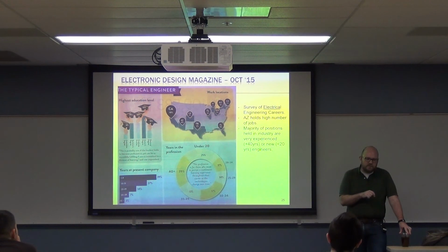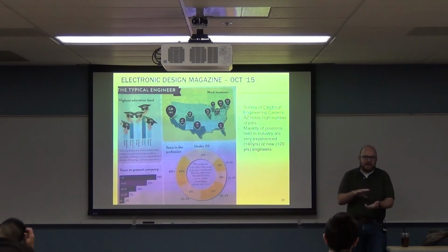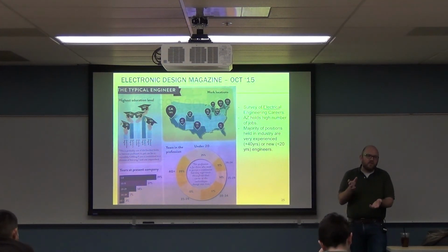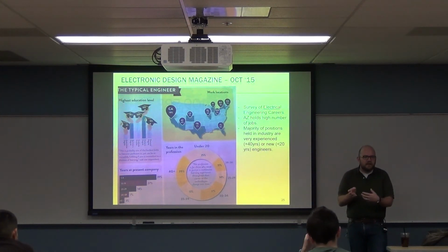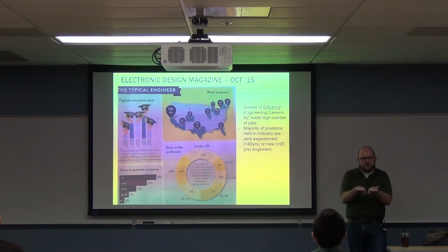The analog students spent a lot of their time writing programs to analyze their circuits, because the design part was kind of easy, but proving that it was going to work was hard. And when they actually went to manufacture these circuits, there was a little bit of work inputting the circuit into the tools, but a lot of work writing the flows and interacting with the flows to check that the circuit was legal. For example, one of the things you're going to learn about is design rule constraints. When I use lithography to manufacture things, there are rules like two pieces of metal can't be too close together.